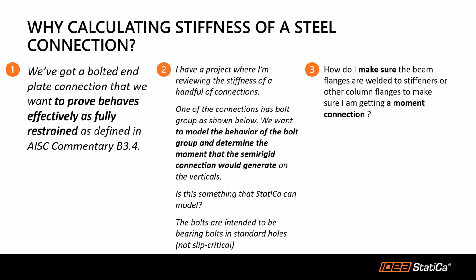So let's start with some user cases that will help us understand how and why the stiffness analysis is important. What I did here is gather some questions or testimonials from users related to the stiffness analysis in IDEA StatiCa. The first user wanted to prove that their moment end plate connections behave effectively as fully restrained connections based on AISC. So this is one of the main uses of the stiffness analysis in IDEA StatiCa.